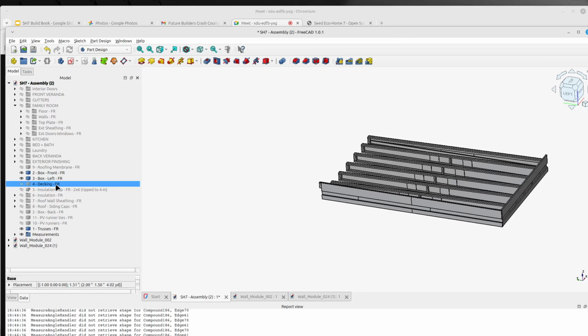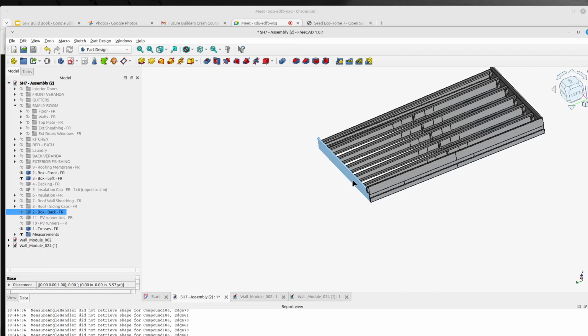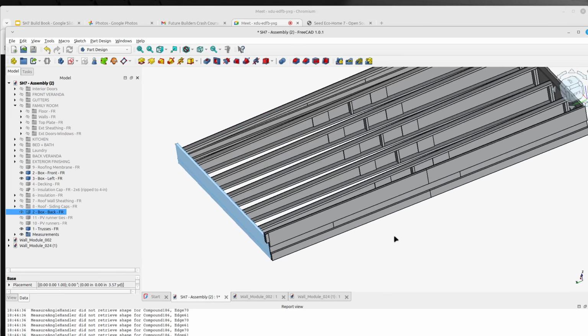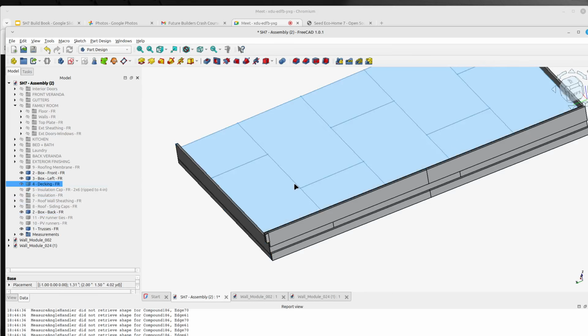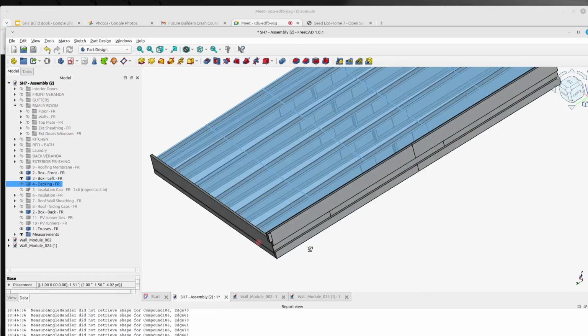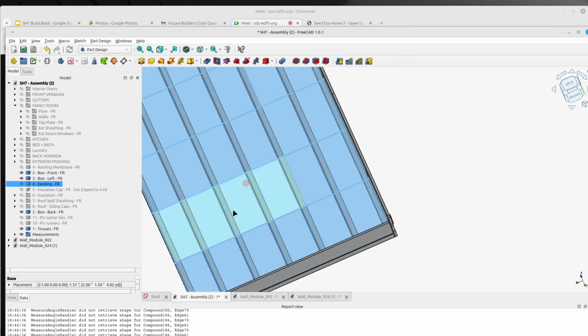Then, let's see, forgot about the back. That also can be built all at the same time. And once again, this is 1/3 of the house, so different teams can be building all of these at the same time. Then you got decking, so that's oriented strand board, 3/4 inch, which if you toggle the visibility, all the seams have to end up over trusses, which happens here. Like that seam right there, it falls on a truss, so this is a full sheet of 8-foot OSB.